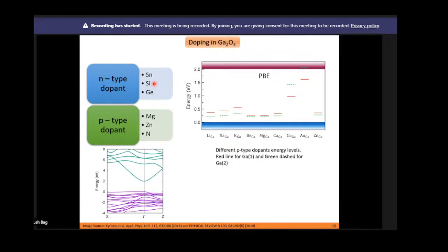Although people have achieved N-type gallium oxide, and we have also achieved this, from the device perspective we need an NP junction or PN junction to get the best possible breakdown voltage. We'll see this again in power devices; breakdown voltage is one important parameter. But since we do not have any P-type gallium oxide, we need to utilize some other P-type material like P-type gallium nitride. On top of this, we can deposit N-type gallium oxide, and then we can get a heterojunction PN junction diode, not a homojunction PN junction diode like your silicon. So these are the things we can do.